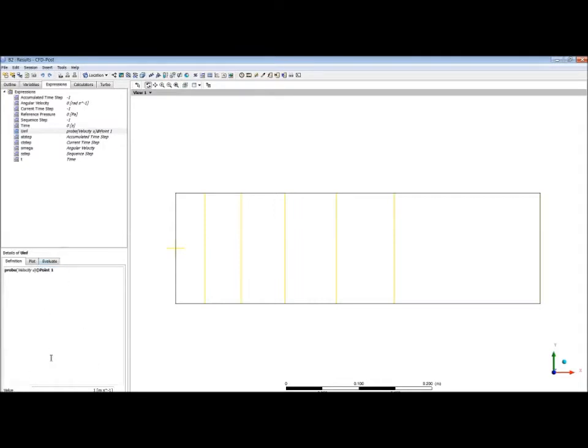So if that's worked out properly, if you click apply, that should tell you 1 meter per second. That's what it's getting: from this point that we drew on here, it's pulling out the velocity at that point, which is the velocity we told it at the inlet, 1 meter per second. So we now have an expression, U inf, which gives us the velocity of the inlet.